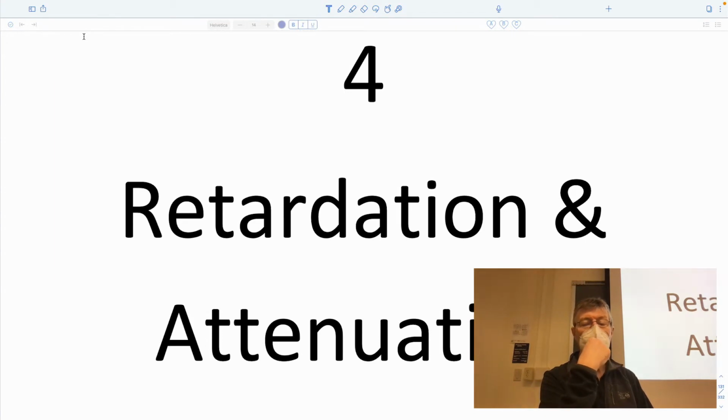And for some classes of contaminants, organic contaminants for instance, they dissolve, but they also are removed from solution by sorbing onto the media they pass through. And since the mass balance that we apply for the flow equations are related to the porous part of the aquifer only, then any amount of mass that is taken out of the system and plastered onto the grains is something that is lost to the overall flow system.